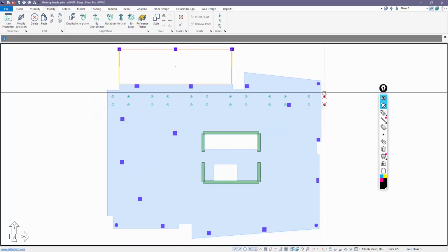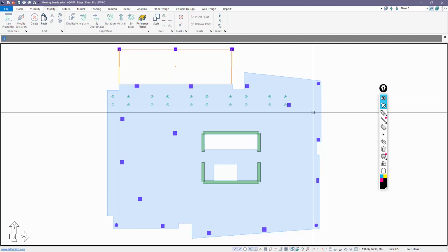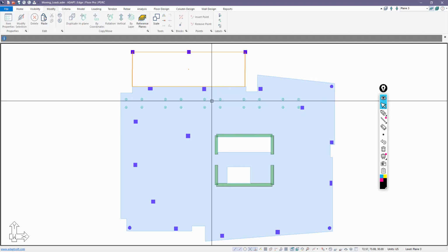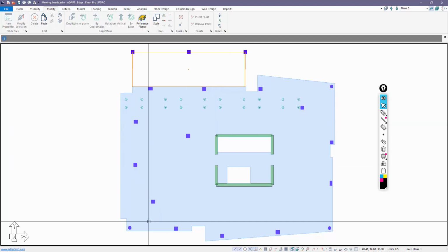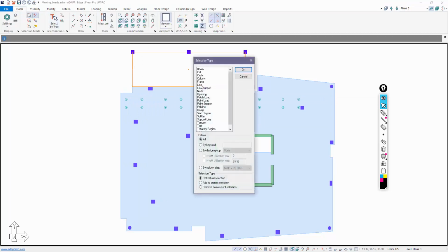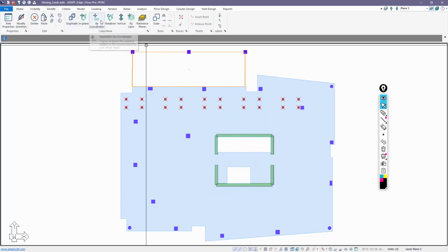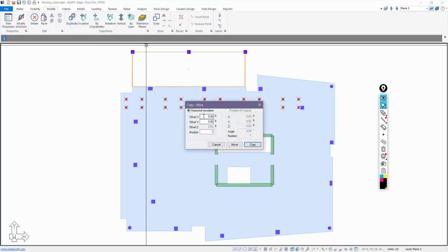And we'll go ahead and just dump out these last two. Okay, there's 1, 2, 3, 4, 5 unique positions, and now I'm going to copy down multiple times. So I'll go ahead and select point loads. I'll select by type, point load, and we're going to go back to modify, and this will be in the negative 15. And let's just copy it down. We'll have more than 10 here, but we'll copy this down. Let's say 5 times also.